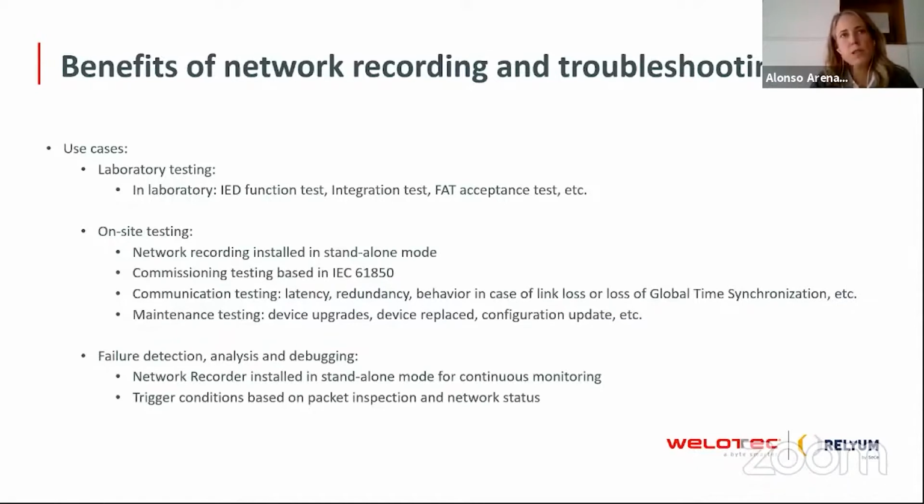But also, compared to other traditional testing tools in the market, this new device can be installed in standalone mode. This is very important, for example, for performing commissioning testing based on the exchange of IEC 61850 traffic and data among the different IEDs, but also for measuring different communication parameters that are critical in this kind of network.